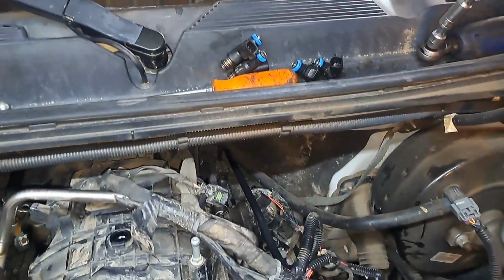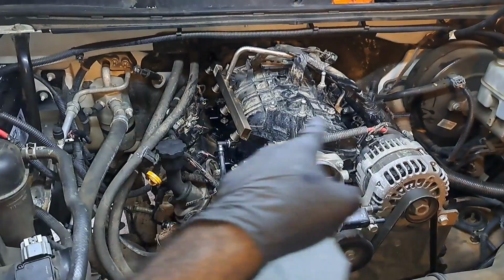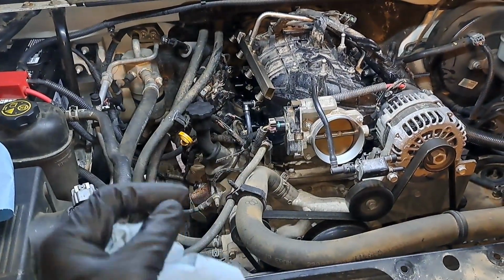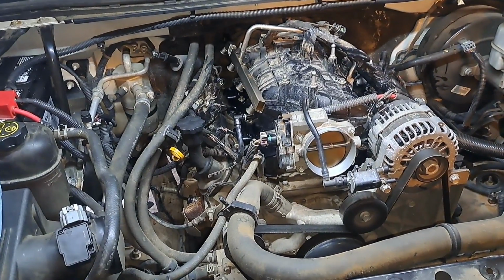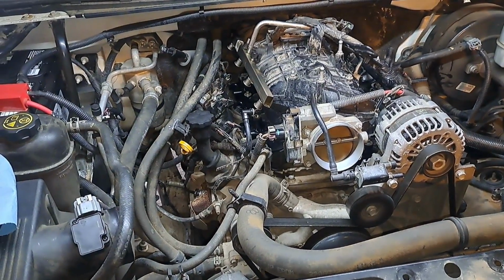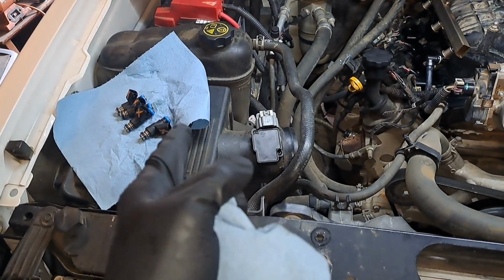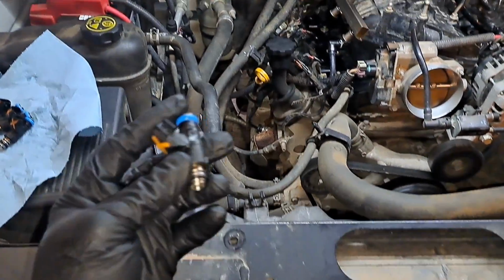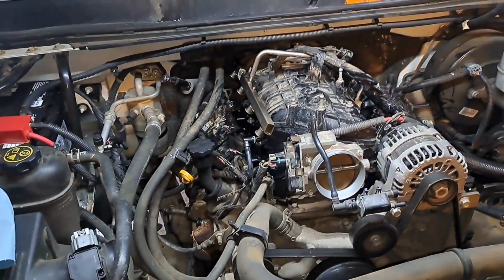The old ones I didn't mark. The ones that I'm changing, the good ones, I didn't mark. So bank 2 is going to bank 1, and bank 1 is going to bank 2, and I have indicated those. I'm going to swap them and see if this code follows the issue, because I'll feel better about changing the injectors if the issue follows the parts. Those things are $400, and it's a possibility the code may not come back if the diesel cleaned them. And I only did it because y'all hate when I clean stuff with diesel. Everybody has their perception on it. So let's get these back installed and see what happens after this drive cycle.